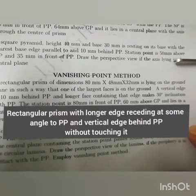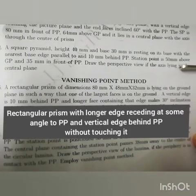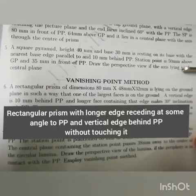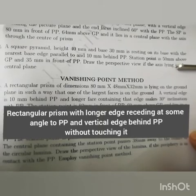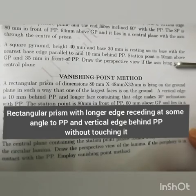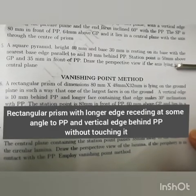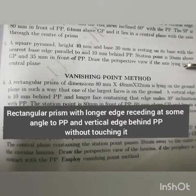Rectangular prism of dimension 80 by 48 by 32 mm is lying on the ground plane in such a way that one of the largest faces is on the ground. A vertical edge is 10 mm behind picture plane and longer face containing that edge makes 30-degree inclination with the picture plane. The station point is 80 mm in front of PP, 60 mm above GP, and lies in a center plane which passes through the center of the prism. Draw the perspective view of the solid by vanishing point method.